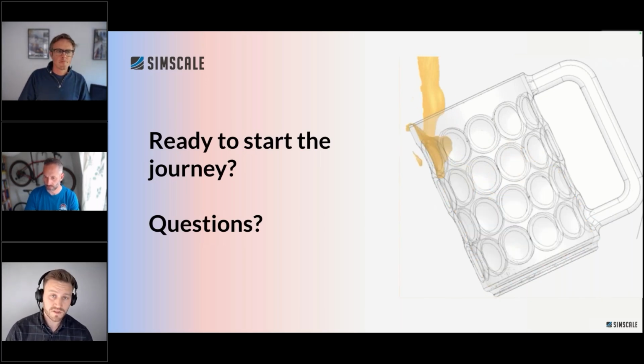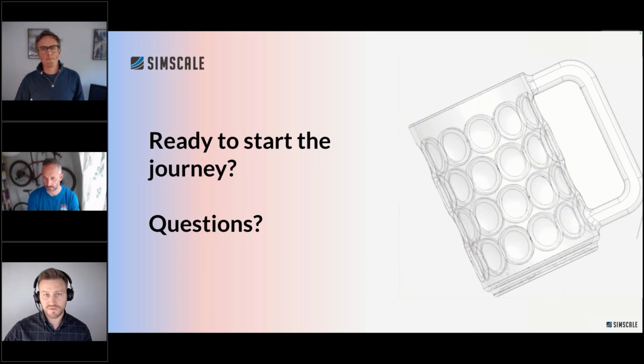It's a really good question. The AI confidence score is a measure of how much the physics AI model is interpolating from the data that it had available in the training data set and how much it's extrapolating outside of that. When we had a new CAD geometry that had diameters that weren't seen in the training data set, the confidence dropped from 80-something to 70-something, signifying that we had a slight change, but we still had confidence in those results to a reasonably high degree.